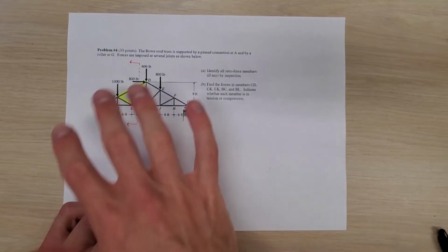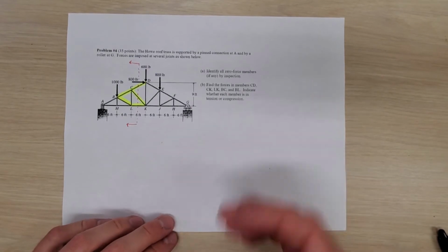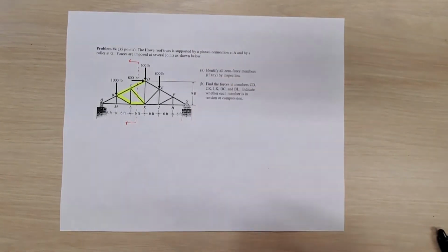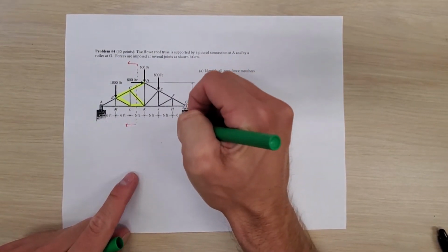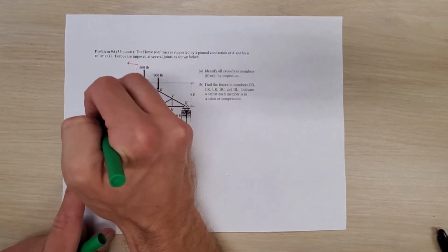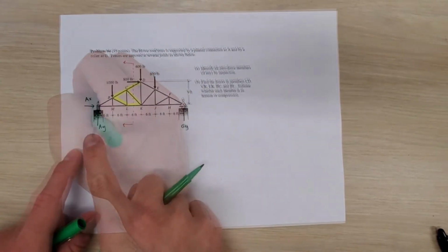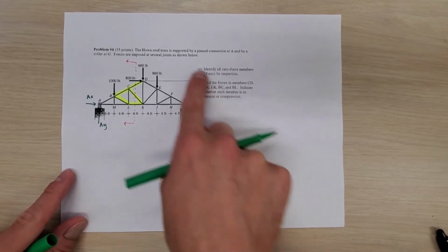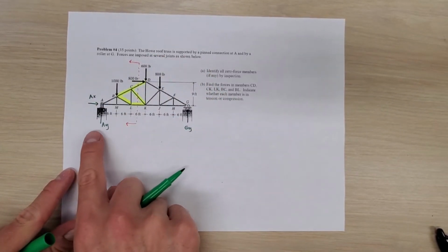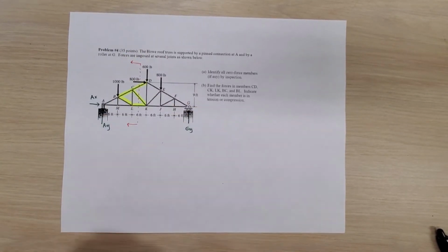Now normally I would have to draw a free body diagram for this whole system to figure things out, but just to make our lives a little bit easier and to save my hand from all this writing, I'm going to take out a green marker and draw the external reaction forces acting on our truss, which are GY, AY, and AX. So these are the reaction forces that we have, and what I'm going to do is look at the whole truss to try and solve for AX and AY so that I can include that in my section cut as I move forward.